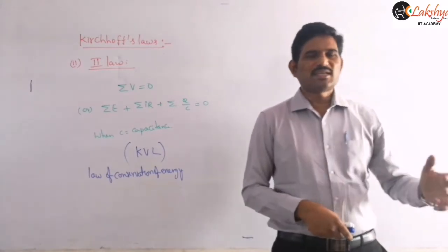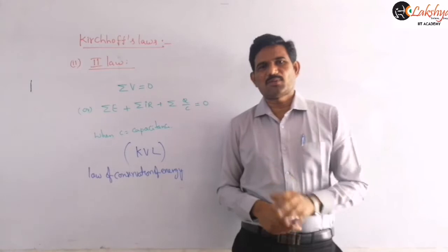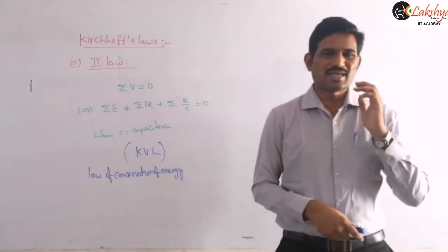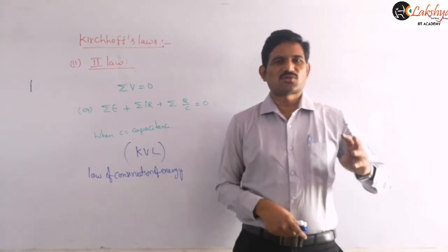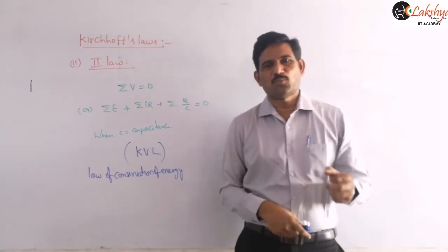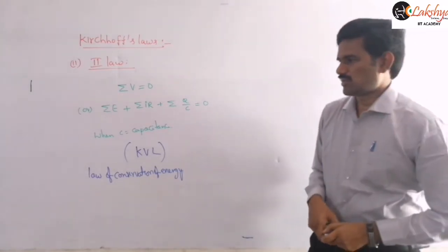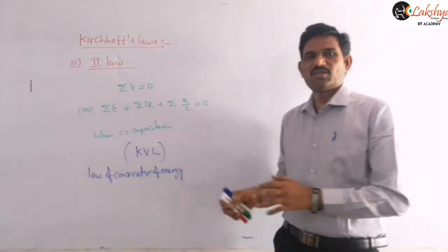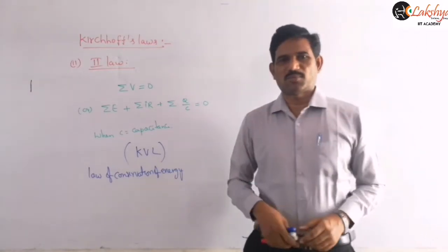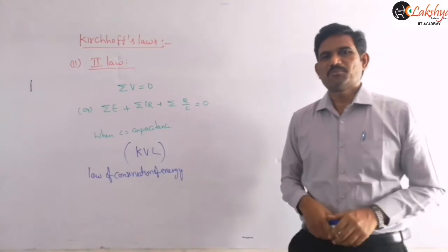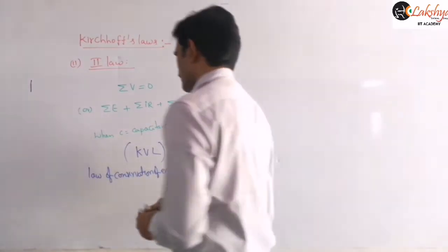If you are not getting any idea how to apply such techniques, then the only way is to apply the Kirchhoff law to find any parameter regarding the circuit, like current in the different branches or potential difference across different points, or when you want to find the effective resistance between the points, right? Such is the importance of the Kirchhoff law. And as I am saying, these Kirchhoff laws are very easy to apply, and if you remember the sign convention, then it is clear.